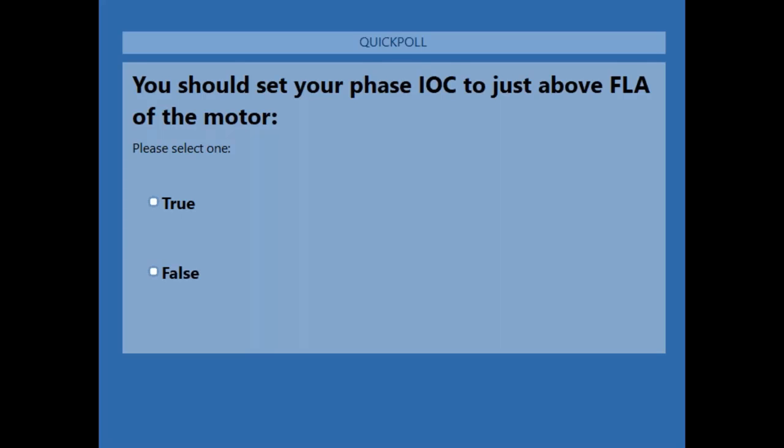Okay, so typically it doesn't affect the cabling of the motor because the CT, I guess it depends, right? It depends on where your CTs are located at, right? So typically your CTs for your one side will be at the contactor. Correct. And so you're just running cable from the contactor to the motor terminal box.